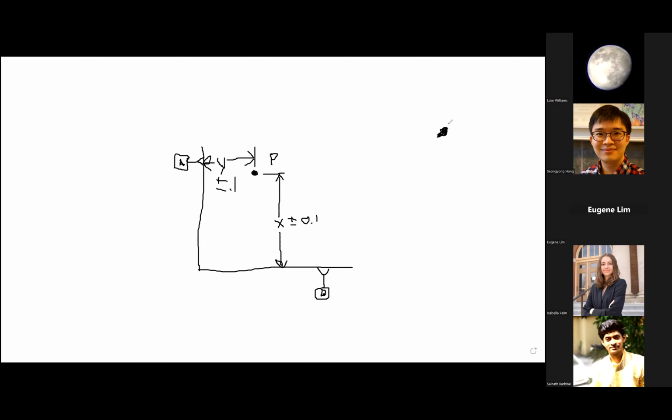So relative to A, we could go plus 0.1. So let's say this line is 0.1 away from the point. And you can go minus 0.1. So you have that much room between those two lines to move left and right. That's sort of the box of your tolerance.